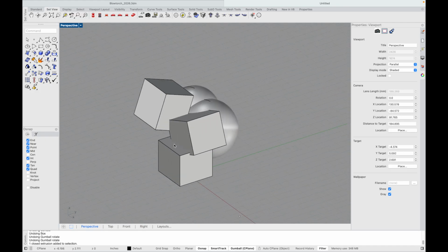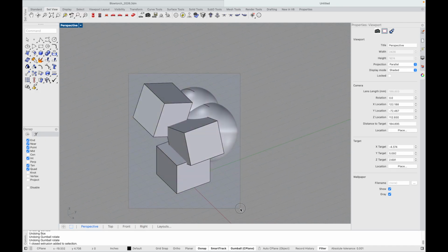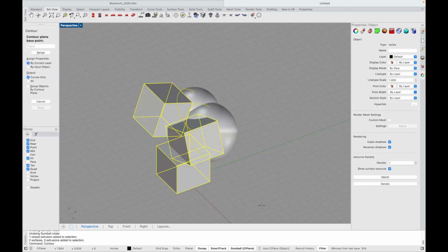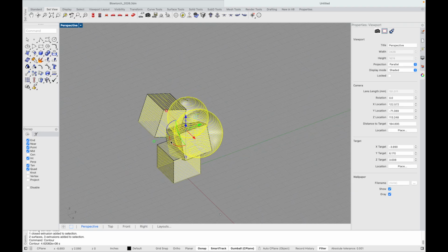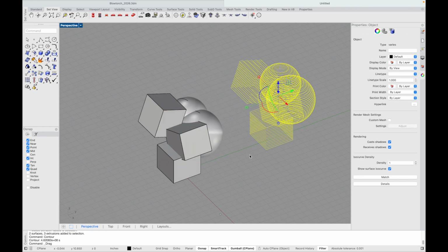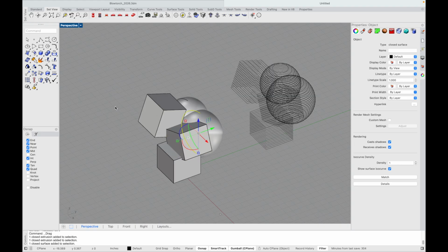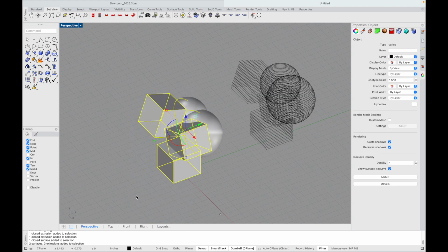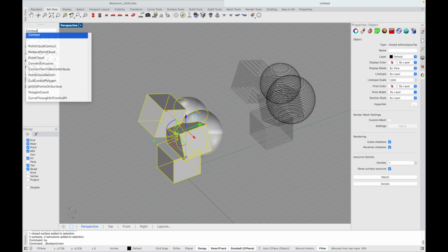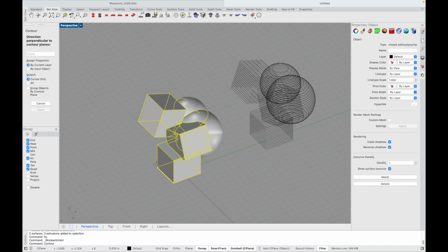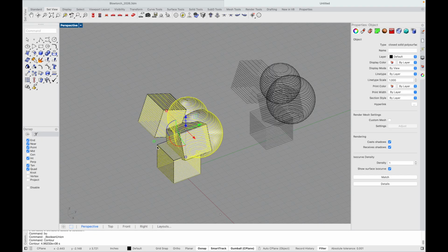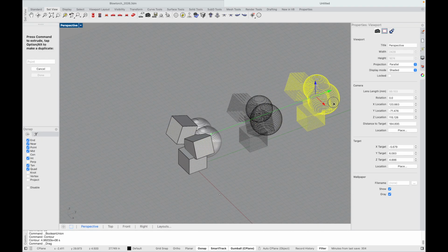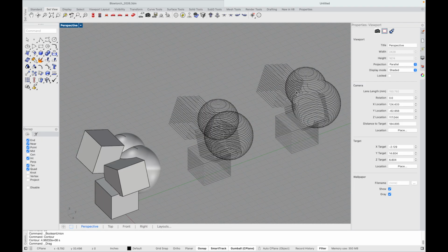You may recall that if I contour, base point, 0.25, let's look at this thing before this stuff is all Booleaned, or joined together, and let's join it all together with a Boolean union, and now let's go to contour again. I'm going to get a different result. So see how much cleaner this is?